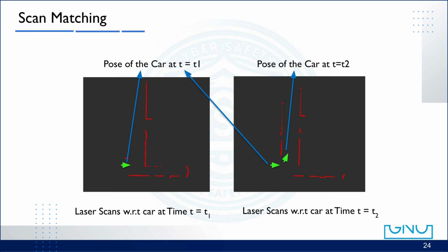This estimated pose change is then fused back into the mapping process, ensuring that the robot maintains an accurate pose while the map is updated. Remember, each laser scan is essentially a point cloud that captures the 2D structure of the environment around the robot. By comparing consecutive scans, we can track motion without relying only on wheel odometry.